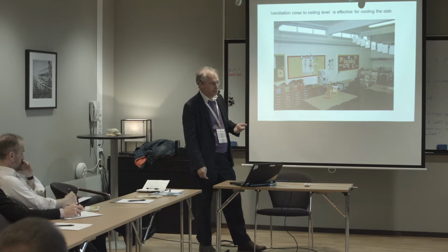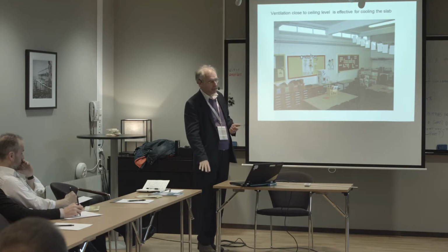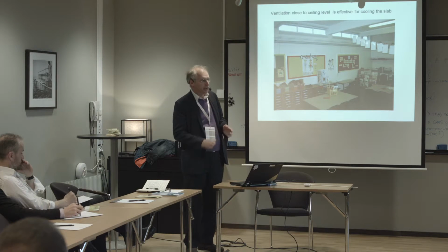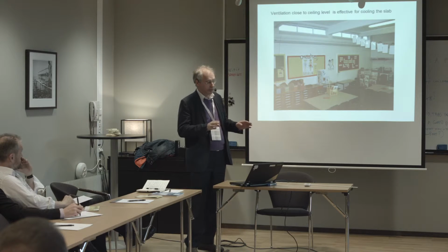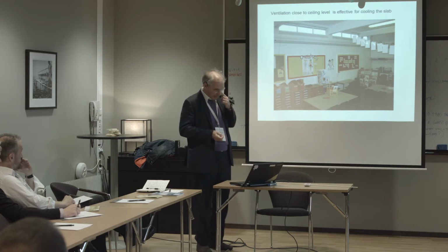The ISO standard talks about the difference in upward radiant temperature and downward radiant temperature, but it measures it at 600 mm off the floor. That is the wrong height, I'm pretty sure, when your temperature sensor is your neck and your head. What we need to talk about is the delta T plane radiant temperature looking upwards, the effect of the hot panel on the top of your head. If you get that right, you can ignore the asymmetric temperature difference, as long as you've got an insulated floor.